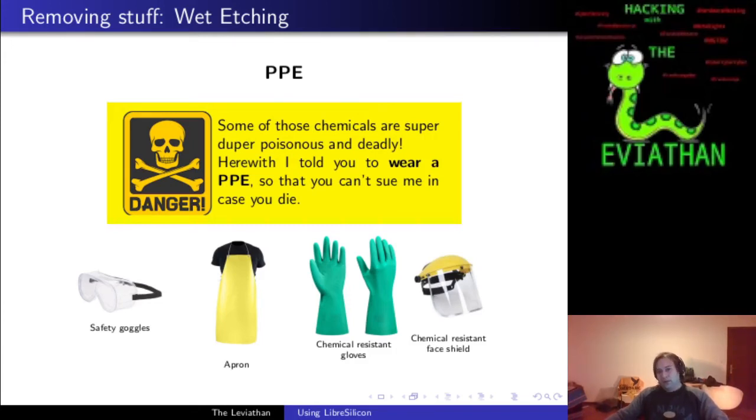Also, a little piece of advice: look at the safety data sheet of each of the chemicals and maybe dilute those chemicals to a degree where a single drop won't just kill you immediately. It's anyway better to have diluted etchants because the slower the etch rate, the better the depth control. In case you really don't know how to properly handle poisonous chemicals, ask someone who knows.